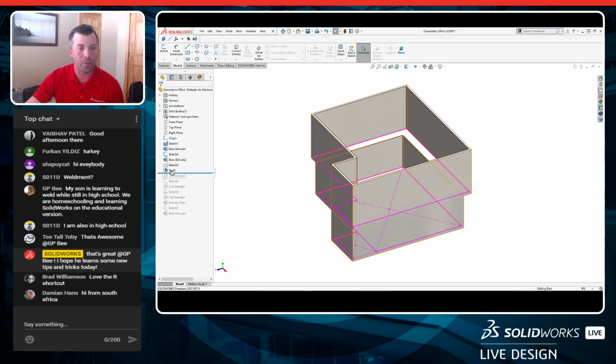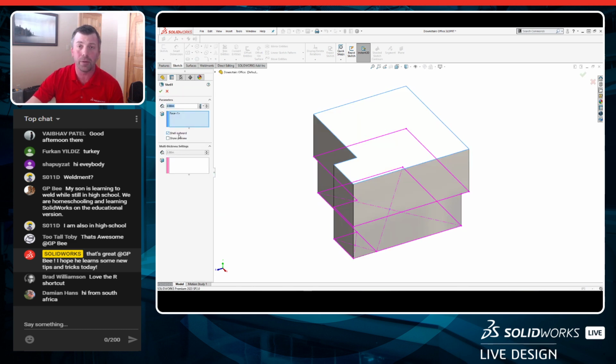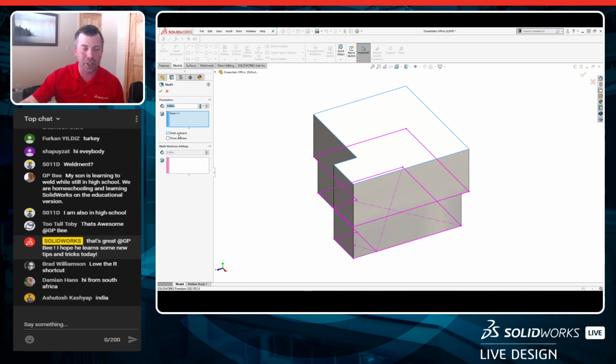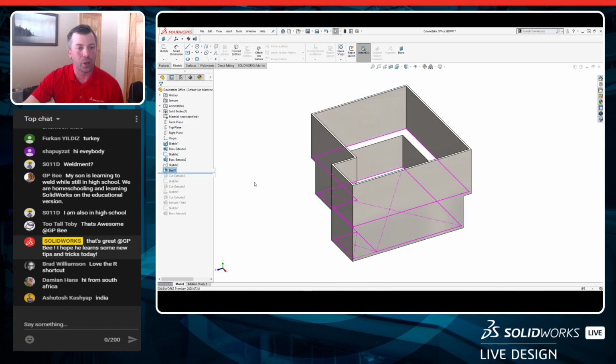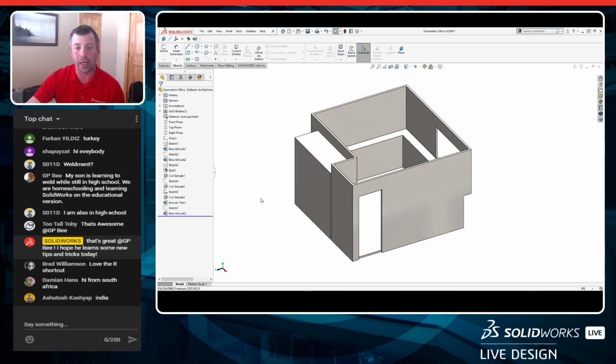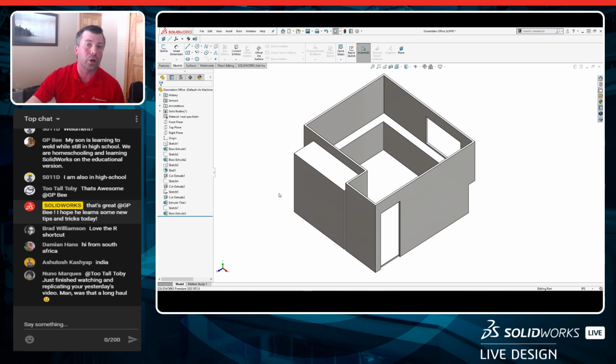In the shell property itself, if you go ahead and edit this, you have the option to shell outward. You want to do that, otherwise you're not going to account for that measurement wall to wall. You'll run into some inaccuracies. So I created the shell. Go ahead and turn off these sketches. And then basically just a few more features, and we had my room to work with. Now again, the reason I did it as a single part here is I wanted to create an assembly, which is where I'm going to start, and then use an in-context approach for the actual desk design.